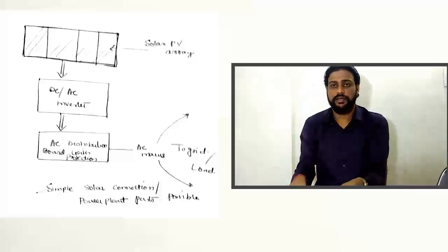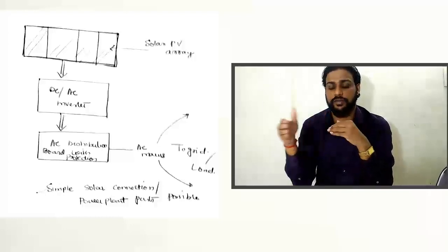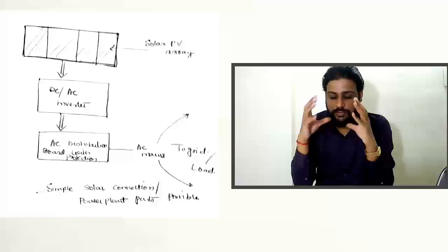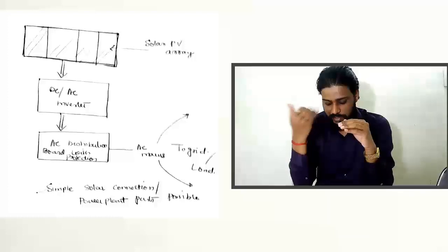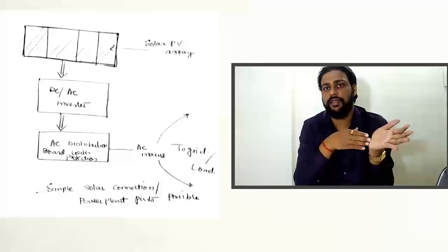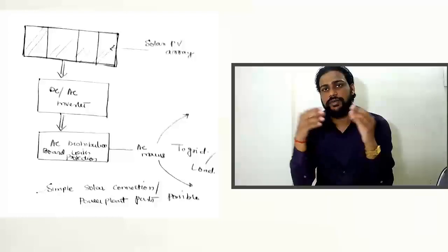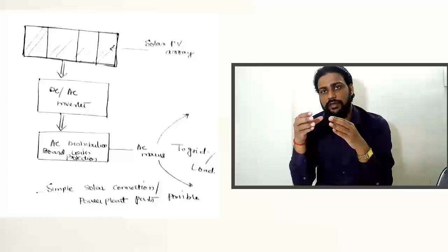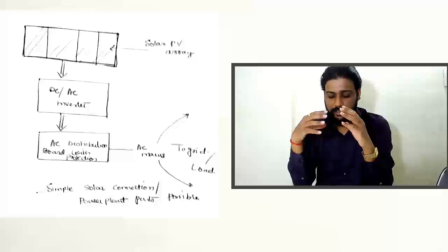And the next power plant which I'd like to discuss before closing this series of lectures is about the gas turbine power plants. In gas turbine power plants, the fuel would be the gas which would be obtained from burning high octane gas or heavy diesel oils, etc. There would be a combustion chamber in which the burning will be happening. You need to supply the air, and the air would be usually in the compressed form. The pressure would be increased before it is supplied, and whenever it is burning, the hot gases are made to expand on the turbine blades, which causes the electricity generation.